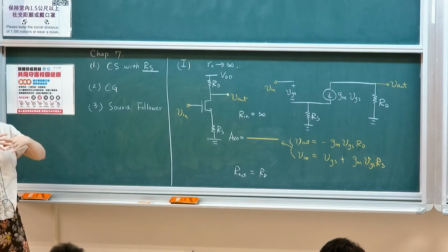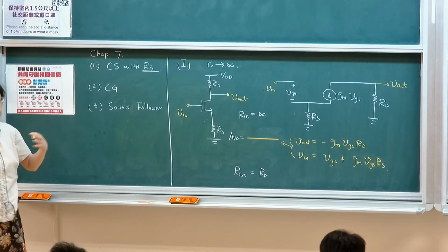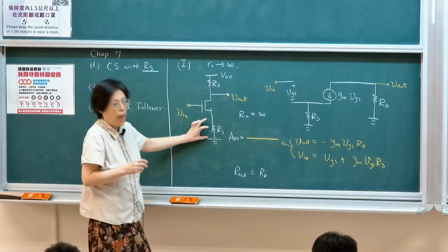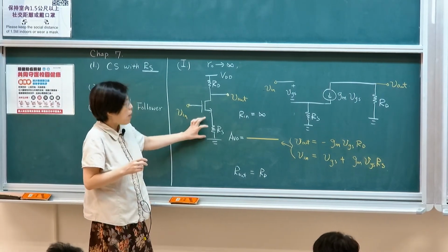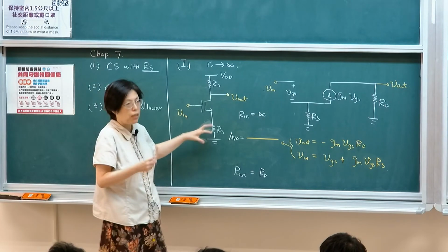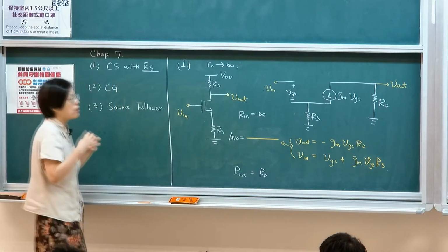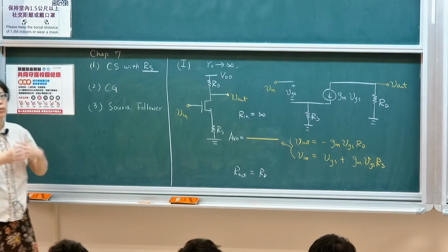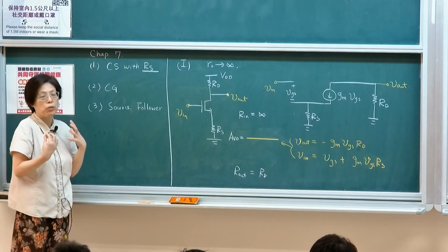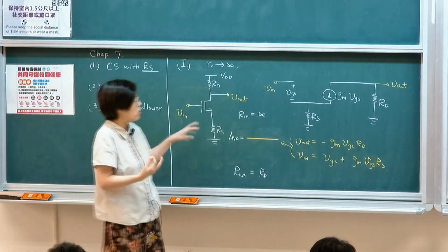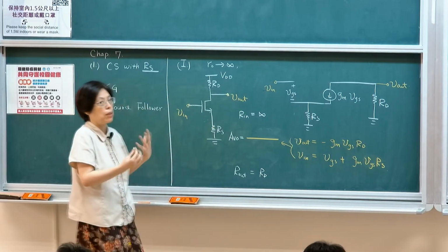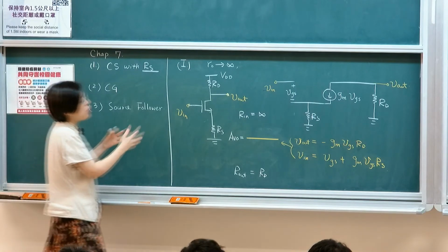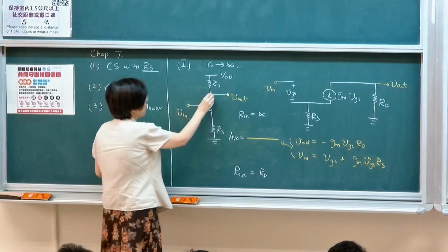The exponential factor leads to explosive current, so you probably need to add attenuation. For MOSFET, you will see it mostly for different reasons, not necessarily to reduce sensitivity, but mostly for linearity. If you want very linear amplification, this type of structure will help. That's the reason why we construct this type of circuit.